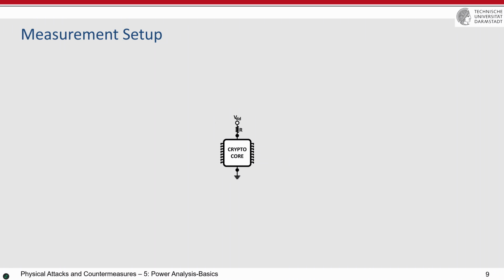And then if you put the resistor at the ground pad here, you not only observe the activities of the chip due to the core, you also see all the currents passing through the ground because of the I/O activities. Meaning that it communicates through the I/O, and you see all this noise in your power measurements.